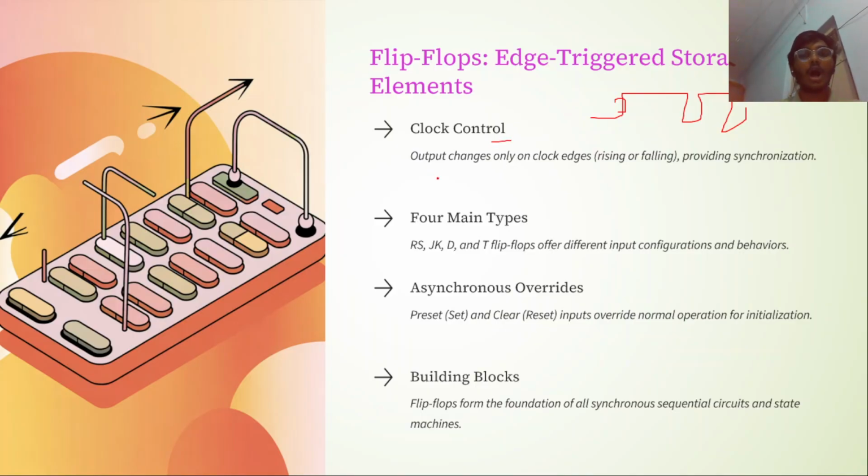Clock control: output changes only on clock edges, rising or falling, synchronously. When the waveform occurs, the output is stored at the edge. Here is the rising part and here is the falling part. On both edges we can store the outputs.